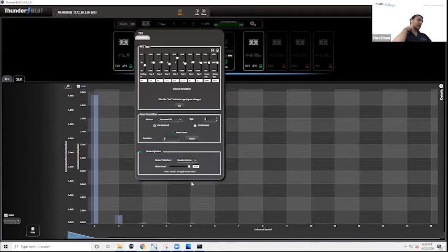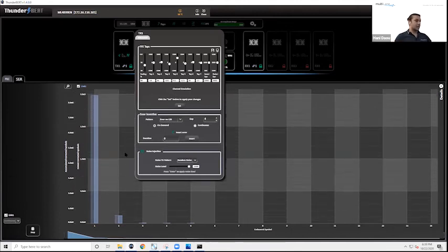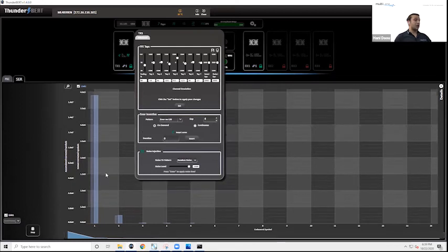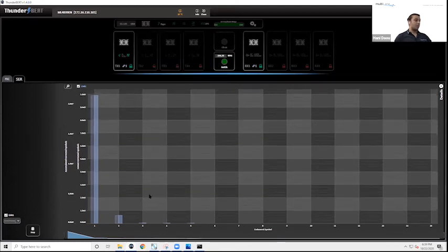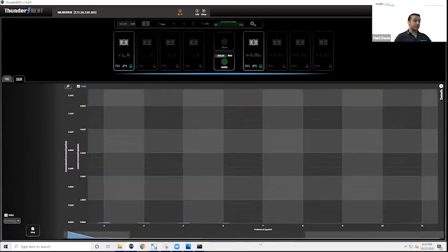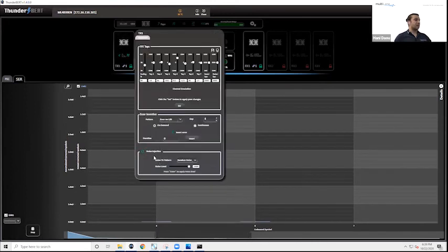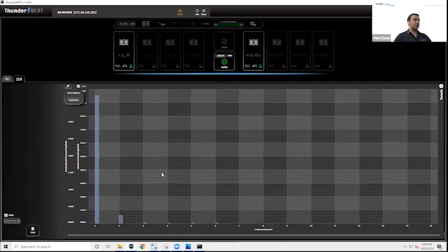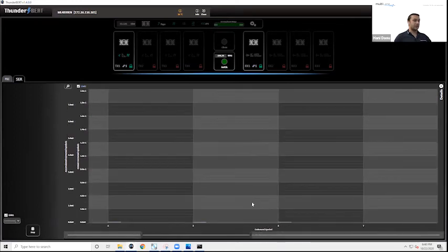So I almost maxed out my noise here, and you can see now that the SER includes code words with 5 symbol errors, with 6 symbol errors. I can even take it a step further, inject some bitwise error injection just to drive the signal crazy. I'll go ahead and auto scale. And now you can see it's barely even keeping lock with symbol errors exceeding 6 symbol errors per code word.